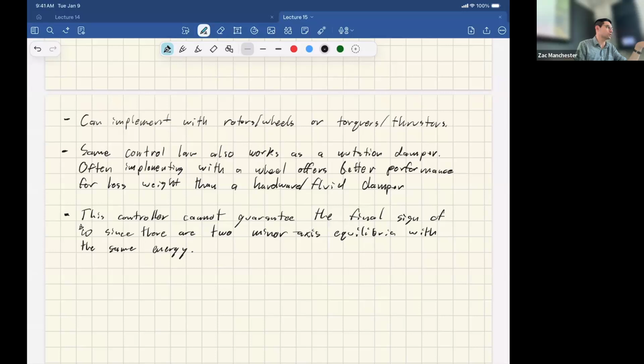It absolutely does show up in signal processing. There are also other fun, weird signal processing things that look kind of like this underdetermined setup, but instead of minimizing the 2 norm, you minimize the 1 norm. That turns out to be very deep in signal processing. That's called compressed sensing, and you can beat the Nyquist limit and all this really awesome stuff.